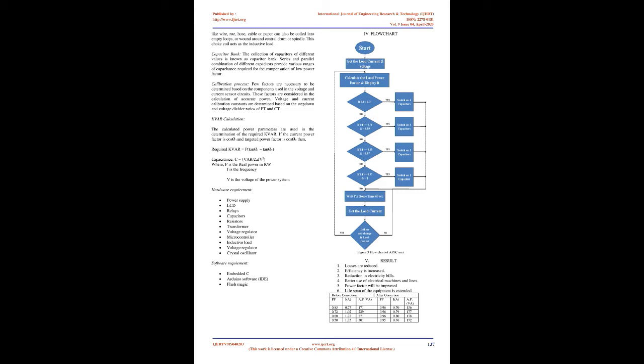2. Principle. Automatic power factor correction, APFC, devices developed using AVR microcontroller. The voltage and current sample is converted into a square wave by the use of zero-cross detector. These samples are fed to the microcontroller at INT0 and INT1, which calculates the difference between the arrival of the two waveforms, which is the phase angle difference. The difference is measured with high accuracy with the help of the internal timer. These time values are calibrated as phase angle and the corresponding power factor is also calculated. This value is displayed on the LCD module. Based on the requirement, the capacitor banks are switched on in steps.